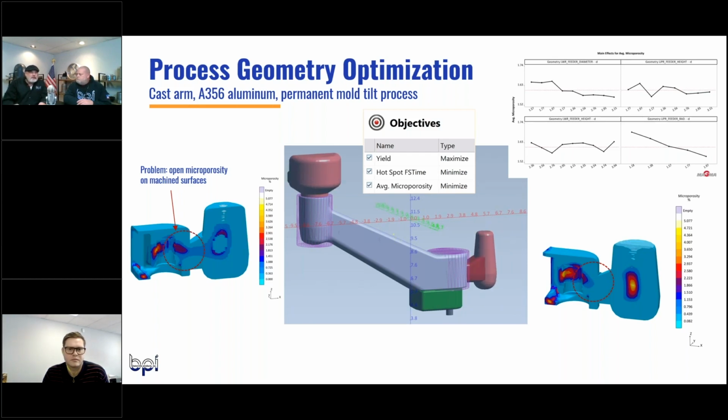Just to reiterate, what the first two slides showed was that the part is in space at liquidus temperature, and then Vadim's software just lets it go in space and set up and cool. Okay, that shows us we've got hot spots, some areas that could cause problems. This is the remedy. This is the software looking at remedies. And what's the best remedy? Where is it going to give us the best results with the least amount of material and cost? Not just material cost, but time cost. If you've got a big riser, you've got to wait till it sets up.